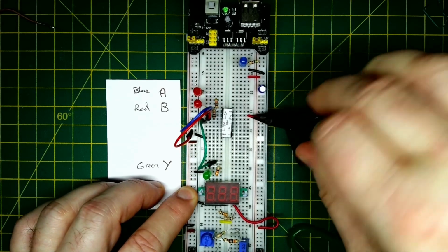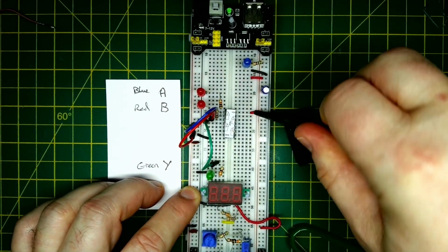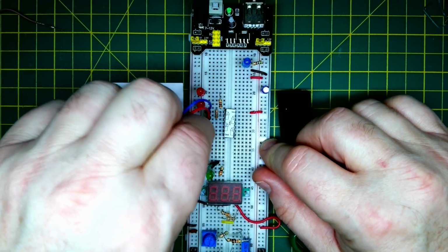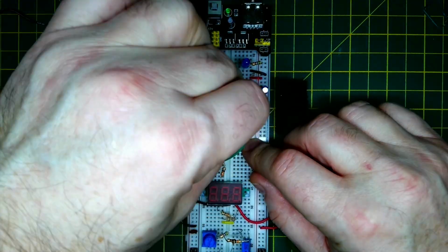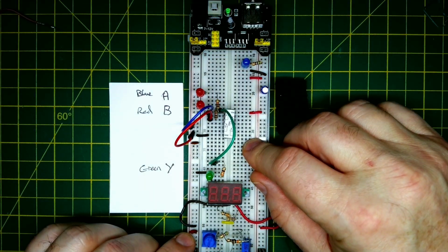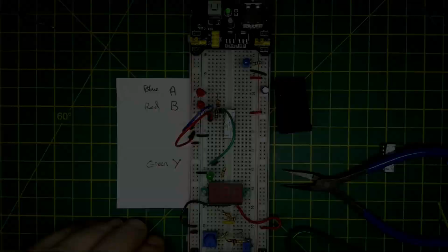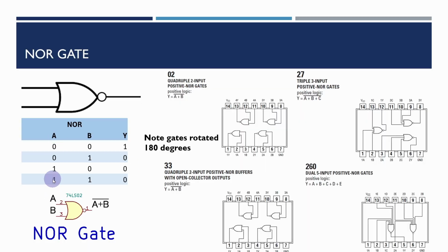That just means that I don't have to rewire the 2 input LEDs. I just need to move this, and then we just need to attach the output to pin 1. Okay, so we now should have those two inputs. So when we turn this on again, because the inputs will default to high, by default without anything connected, then we would expect to see a 0 coming out of here. And then the only time we're going to get a 1 is when they're both connected to ground.